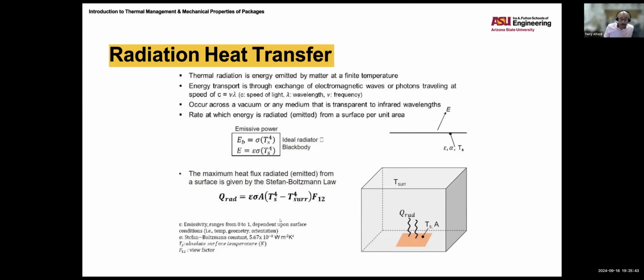And then earlier, someone asked about the different paths. So if we look at the heat transfer path in the mold, here we have die attach. Here's our die, silicon. We're going to get some heat out. Well, it's going to be in contact with the board, in this particular case, the substrate. And we will use the planes, the metal traces, to also help remove heat.